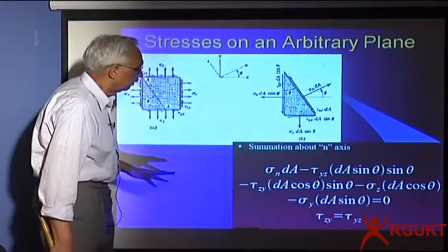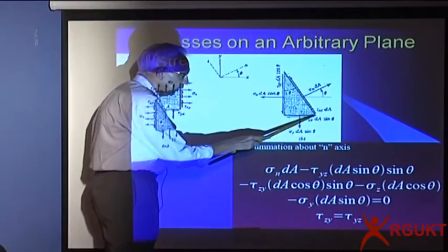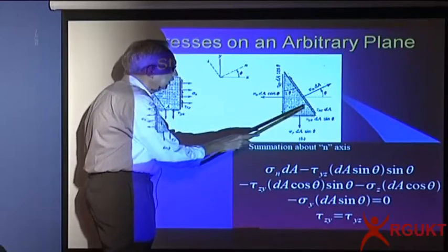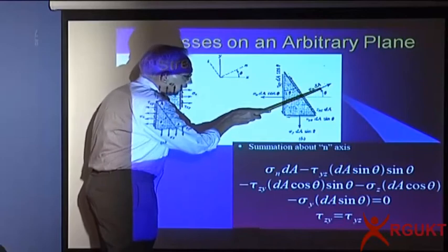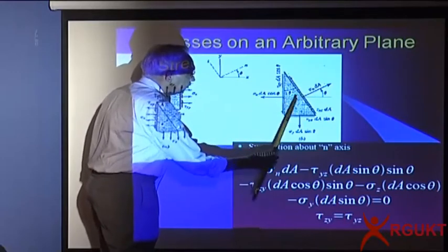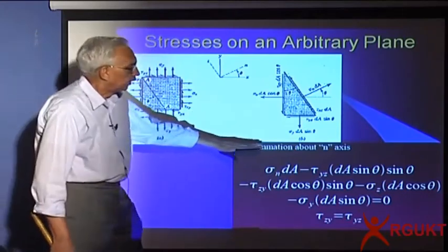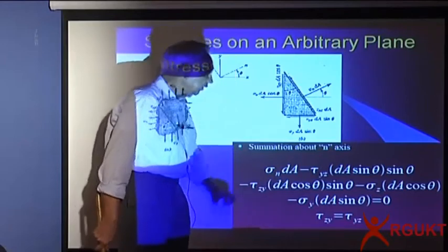If I now resolve into various components, we also have to take the components of the shear stresses. So shear stress into this area. Now the component in this direction, I'll have to take cos theta, whereas perpendicular to that would be sin theta. Summing up the forces along the n axis or normal axis, I get this expression.